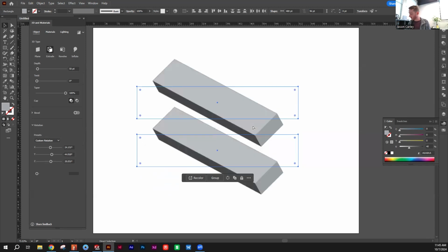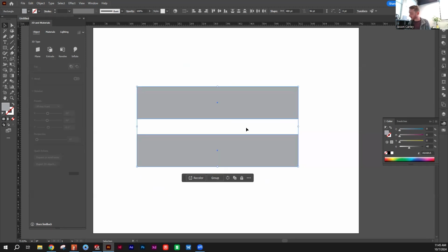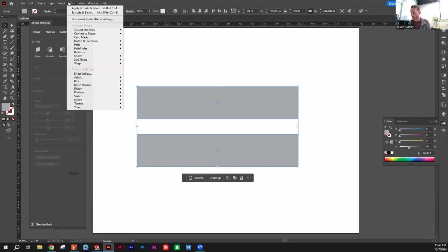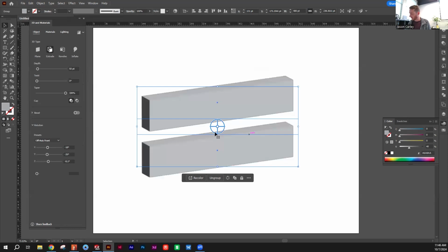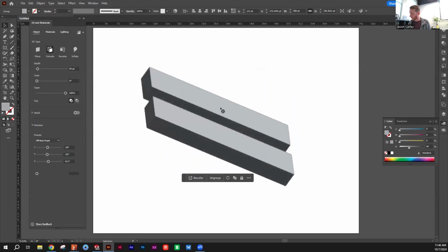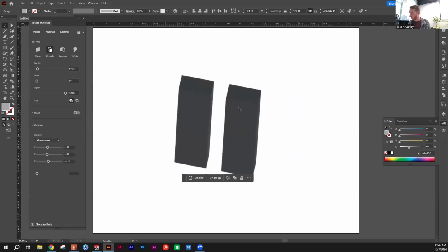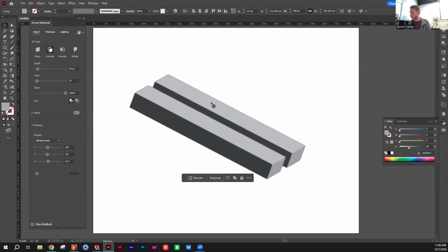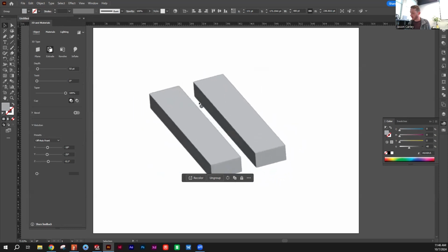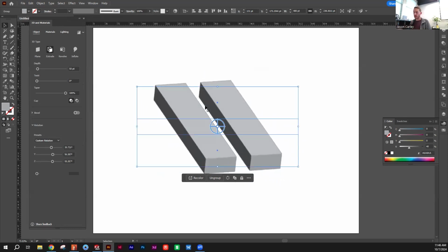So I'm just going to backtrack a little bit to when I had it in my floor plan here. The thing I'm going to do differently is group these two objects. Now that it's in a group, if I use that same tool, it's going to rotate the two of them about a shared coordinate system, so that floor plan will remain linked.